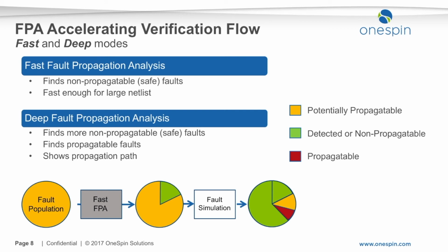At this point, target coverage will often not have been achieved, making it necessary to manually analyze the remaining yellow faults. This time-consuming process either results in improvement to the simulation environment to demonstrate that more faults are detected, or it provides arguments to claim that some faults are safe. Both of these strategies aim at improving the diagnostic coverage figure.